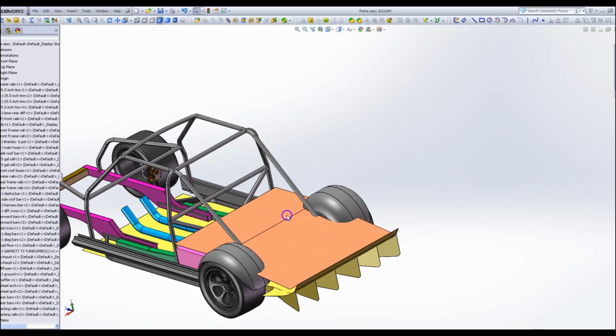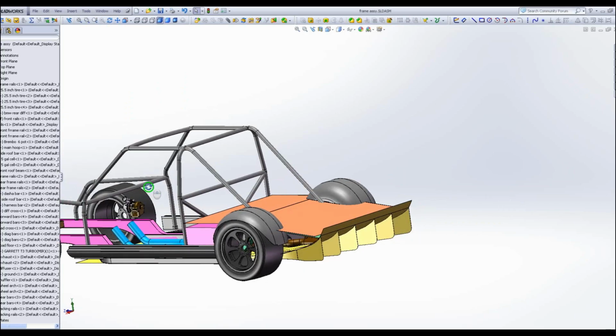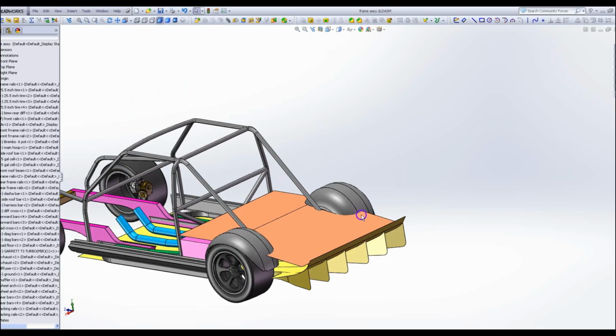So this is the load floor. This is going to have a hatchback, so all this area will be accessible by opening the hatch up. So you can throw pretty large stuff in here. These are the stock fender well approximations of them. And then I'm just going to put a piece of sheet metal in between, just roll it on my bead roller and then weld that in. So it basically widens it.